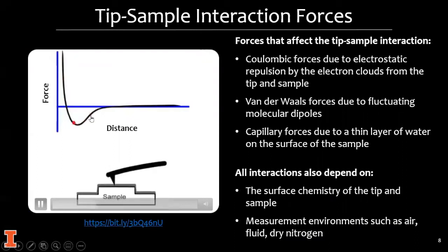As it approaches the surface, it'll begin to feel some surface forces and then eventually make contact, which would be this part of the curve here in the contact region. At a set trigger amount of force or distance that the tip travels, it'll then begin to retract away. And this would be the part where you can see some pull-off forces or adhesion. And eventually the bending of the cantilever will overcome that and snap back to the 0 force baseline.